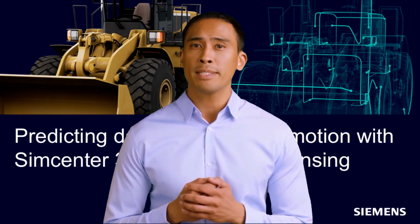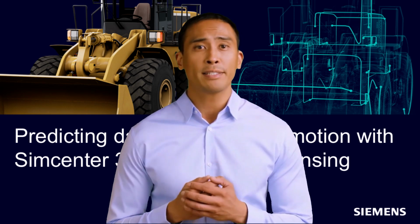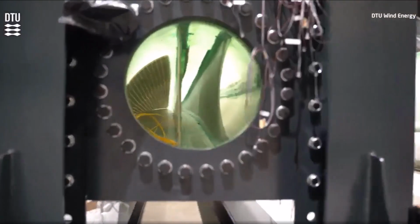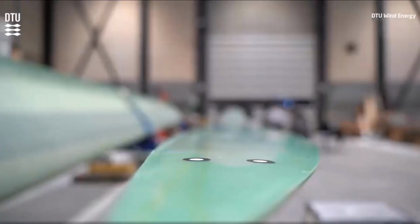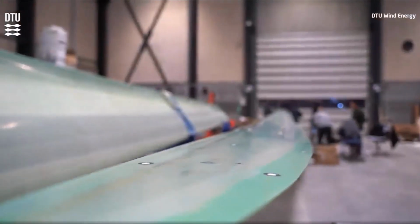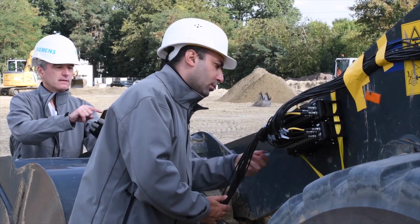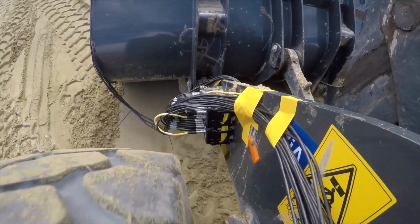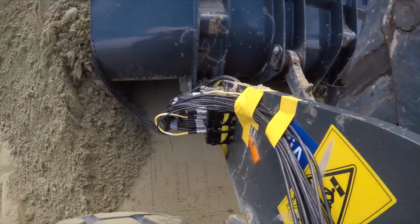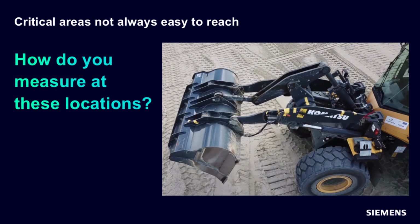To measure performance of a physical product or component, you need to outfit the test subject with a number of sensors, like strain gauges and accelerometers, and ensure you have the data acquisition system channels for those sensors. This can be costly for larger structures. Attaching sensors to the testing specimen takes time, and when the geometry is complex, it might even be impossible to fit a sensor into a critical area you want to measure. So how can you measure these impossible-to-reach locations?